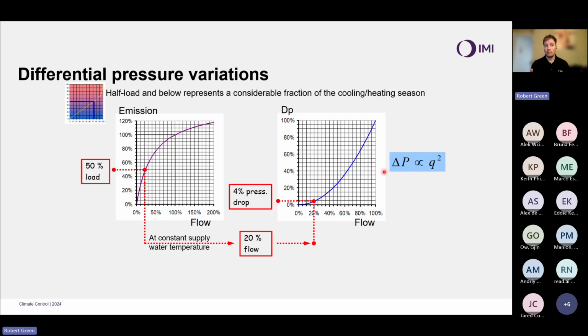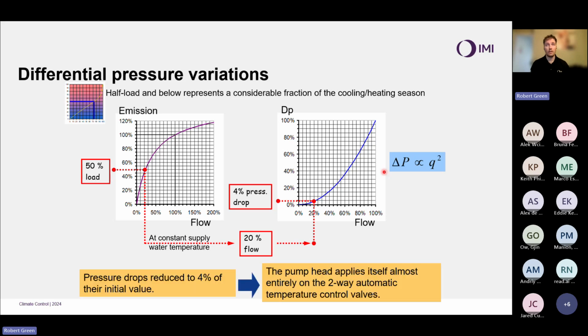And where do they go? Well, if we have a pump running constant head, we are still emitting that design head, that 100 kilopascals, 150 kilopascals, whatever that design pump head needs to be to satisfy my full load. But we have some dynamic devices in the system. And in a basic system, those are the control valves, because these are the devices that are moving to change the load in the system. We're controlling my temperature throughout the system, or controlling my HVAC temperatures with these control valves.